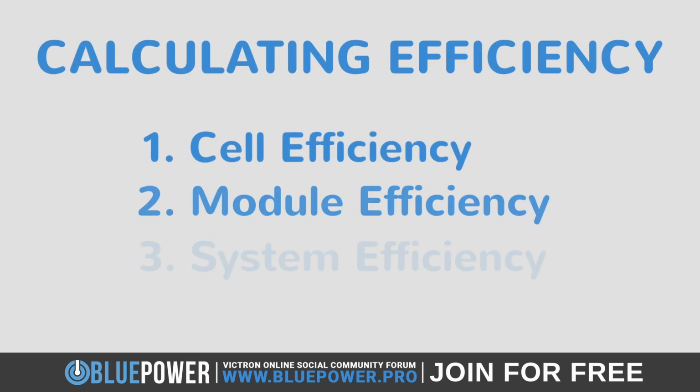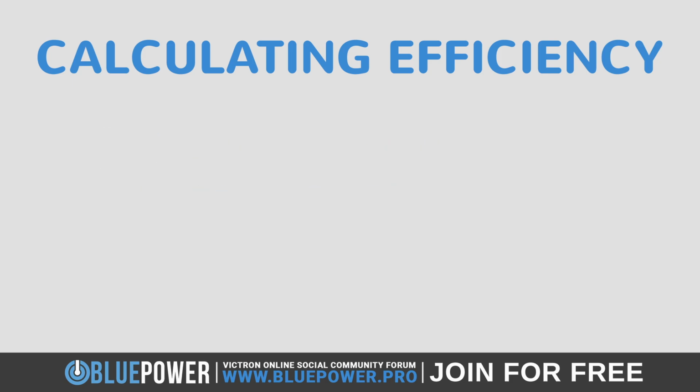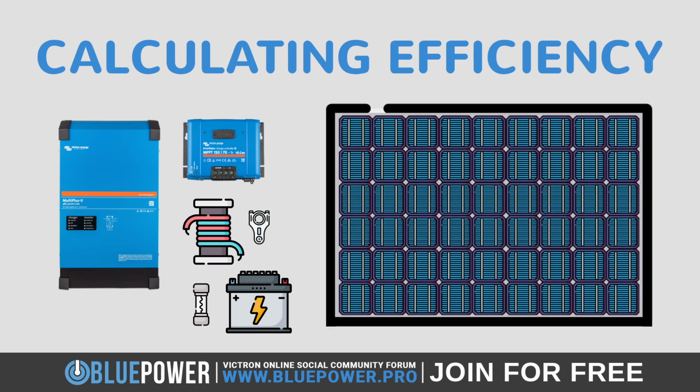Great, we now know how to calculate both the total solar module and cell efficiency, but what about the total system efficiency? Well, this gets tricky because no two systems are the same. However, in order to do this, you need to factor in the efficiency rating of the inverter, MPPT charge controller, wiring, fuses, and even the battery, together with the solar module. Fortunately, most of these devices will have an efficiency rating on their spec sheets.